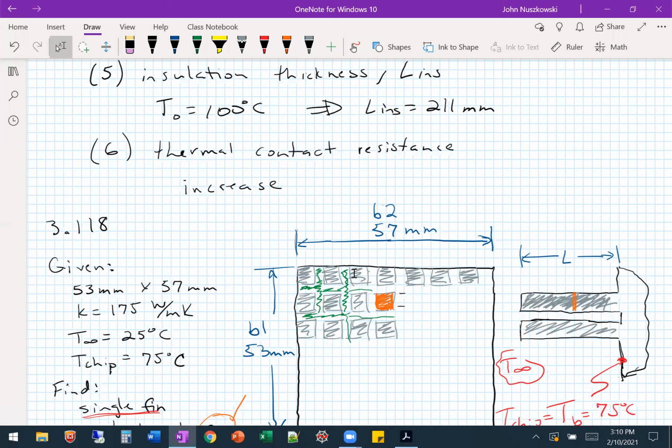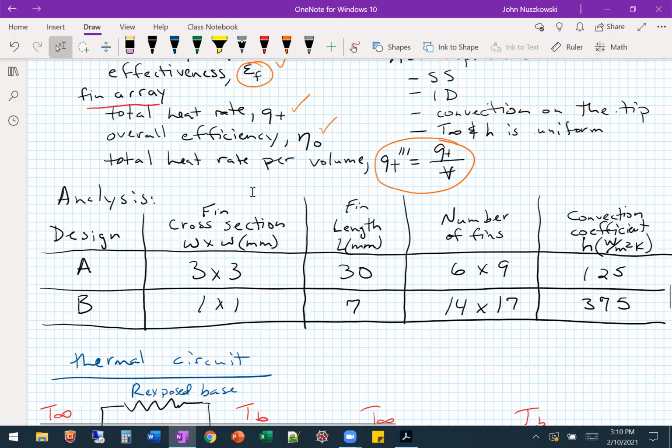Is it our manufacturing process? The manufacturing process is one big one. You need a process to get that space in between them, and to do it cost effectively, not just being able to do it, but being able to do it at a reasonable cost. The other is the convection coefficient, which we'll talk about more in later chapters. If the spaces between the channels get even smaller, you have to have a higher and higher fan to blow air through there because of the pressure drop from that small space.